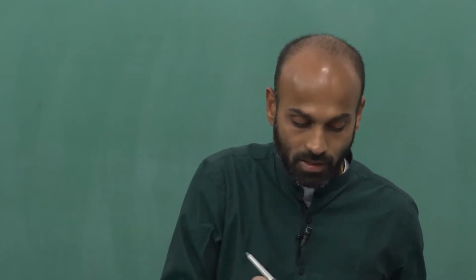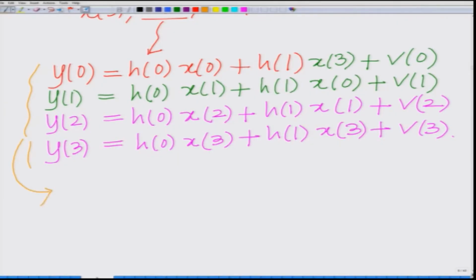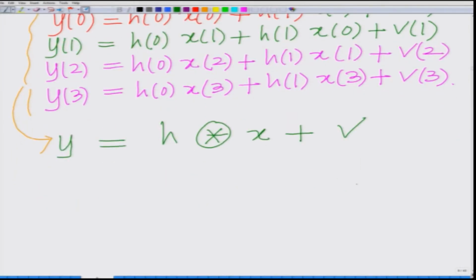That is the key operation, the advantage that the addition of the cyclic prefix is giving us. We saw this in great detail yesterday: because of the cyclic prefix, y becomes the circular convolution of H with X in the presence of additive noise.